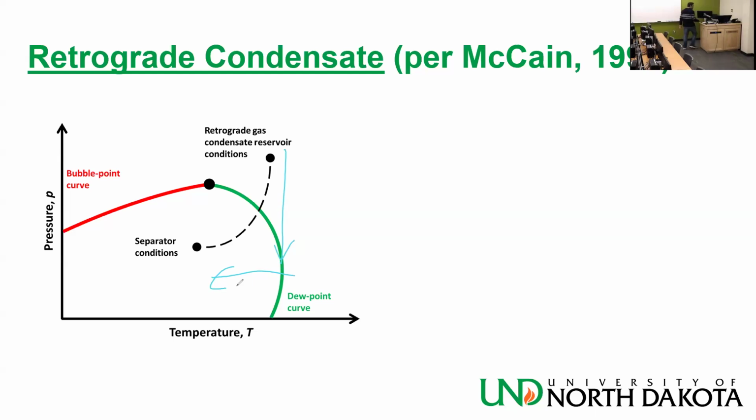So what people do, and they do that in Algeria, they do that in Peru, we do what we call liquid blocking. We drill wells around the well that we tend to produce from, and we inject, trying to maintain the temperature and the pressure in the reservoir within the conditions that are going to give us the most liquid so we can get it out. It's very, very hard to maintain liquid blocking. You can get it to work a little bit, but it's very easy to lose it.